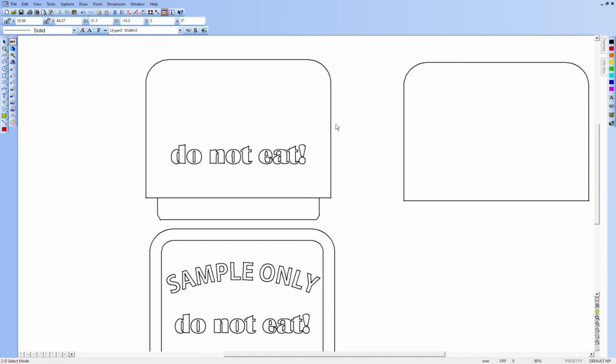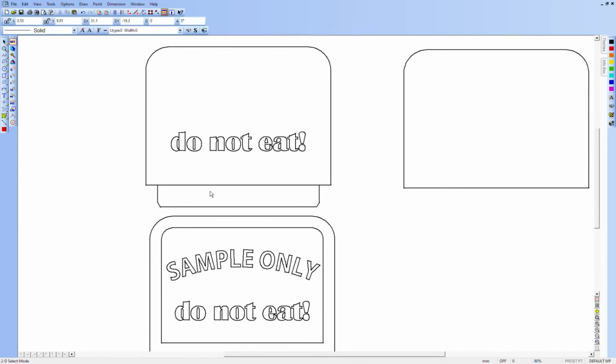In terms of remaining elements, we now have a little problem down here. If we laser cut this part as it is drawn right now, we're going to lose the tongue because the laser will cut right across the top of that tongue, separating it from everything else. So what we can do in DesignCAD that we can't do in SOLIDWORKS is to modify that line. We'll select that line and delete it.